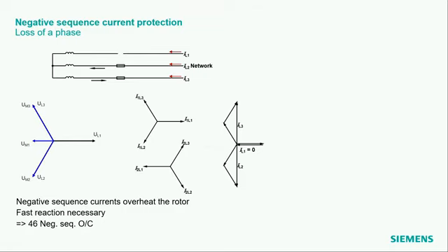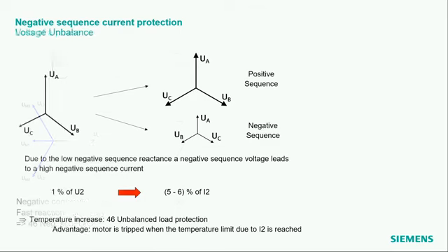The speed difference is almost twice the rotor speed. We can say it in that way, not very precisely, but basically like that. And if you look into the equivalent diagram of the motor, then you see for these negative sequence currents, you have a higher slip. It's 2 minus S, S being the slip for the positive sequence current, and this leads to a relatively high current in the rotor due to this negative sequence current, if you compare it to the positive sequence current.